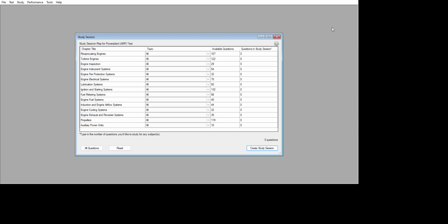Why does the turbine engine ignition system require high energy? To ignite the fuel under condition of high altitude and low temperature. Prior to performing an engine trimming, you should obtain the true temperature comparable to that of the air that enters the engine.